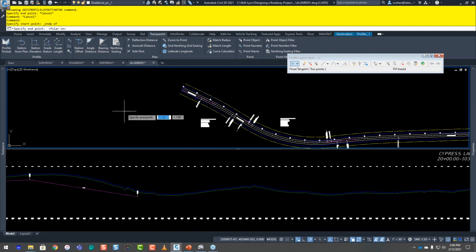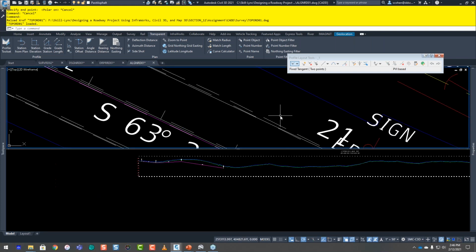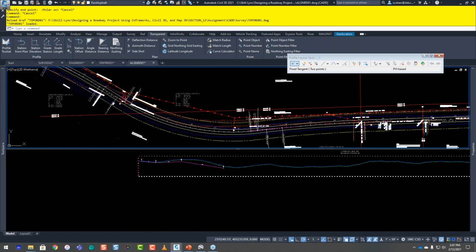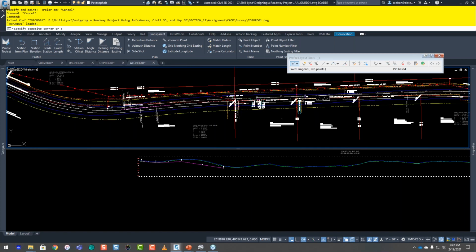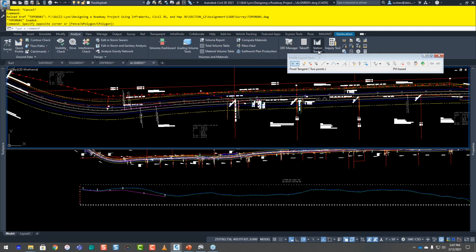So let's go ahead and right click and reload this here. I've got my palette in the other monitor here, so let's go ahead and reload. So I've got my topo, and let's say I want to go to this location here. Where am I here? So my tracker should be on. I'm not seeing it. So analyze, tracker, and then all viewports. There we go. So now I'm up here.